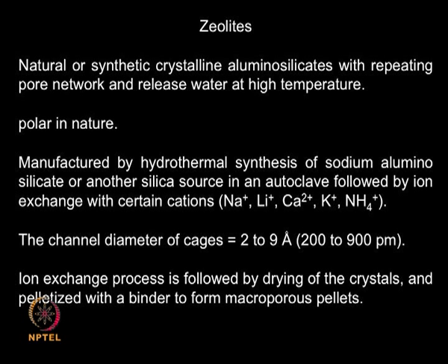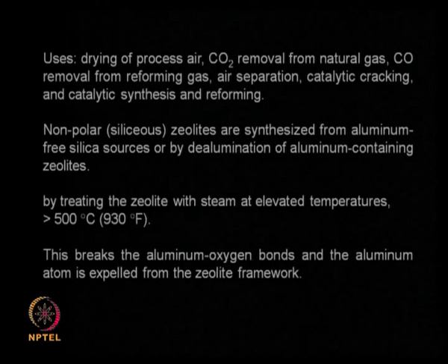So once you have prepared your zeolite using ion exchange, you go into drying, and then it goes into pelletization and binding to form macroporous pellets. Okay. So in a solid material, solid adsorbent, there is always something called pelletization and binding, so that the adsorbent is mechanically stable and it has a good shelf life as well. So zeolite is another adsorbent which is widely used nowadays for gases as well as for moisture removal.